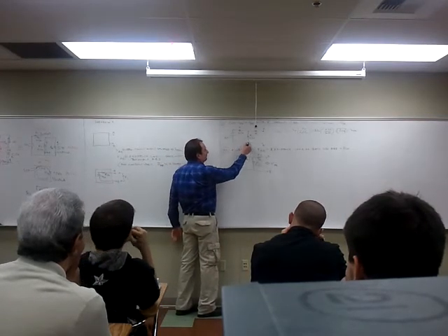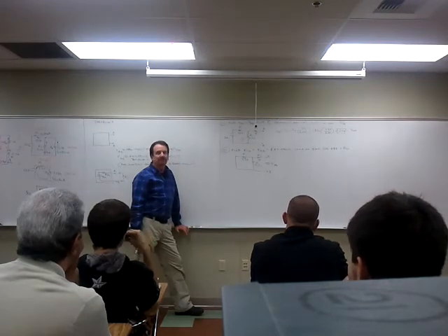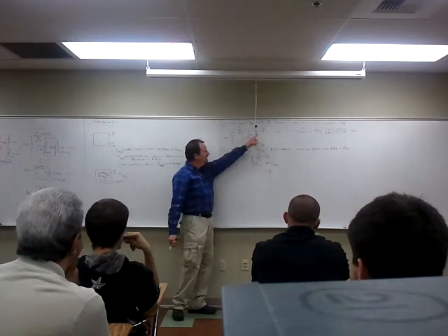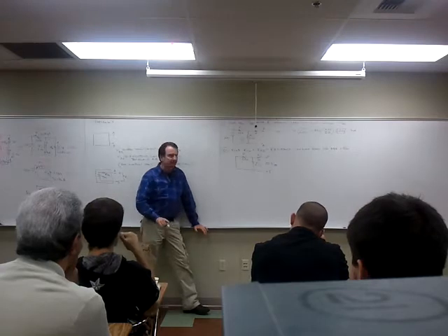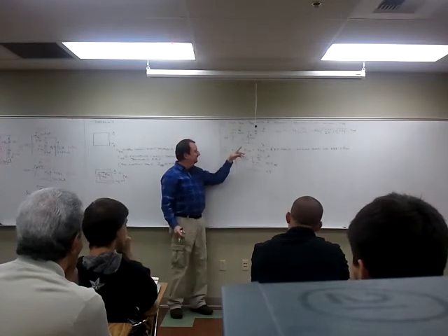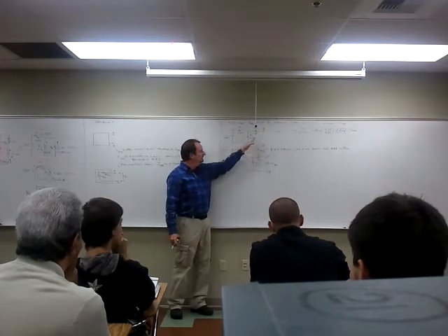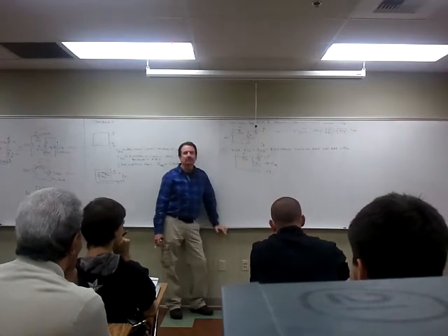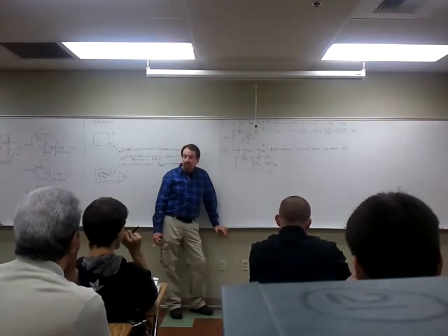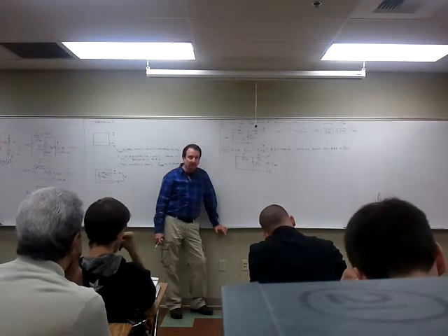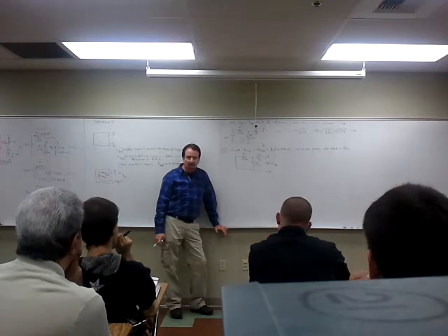Wouldn't current leave here and flow through R2 and R1? So it's 3.3K plus 2.2K is 5.5K, isn't it? This resistor is not even in the circuit because there's no path. So from the point of view of this source, what does our total mean? It means, what is the source seeing as a load on it? The source sees just R1 and R2 across it. That's our total in this circuit. But our Thevenin is never our total from the point of view of the source.